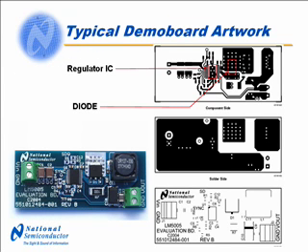Shown on this slide is the same 2.5 amp evaluation board that we looked at earlier. This 2-layer PC board has several features to aid the thermal design. The 2 highest dissipating devices are the regulator IC and the diode. Each of these devices have exposed underside pads, and the PC board has several vias to couple the heat to the larger copper areas, aiding in power dissipation.